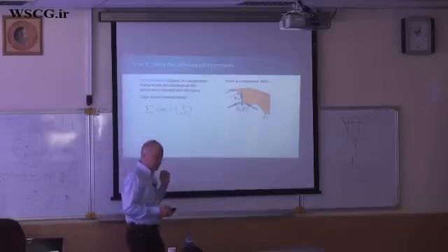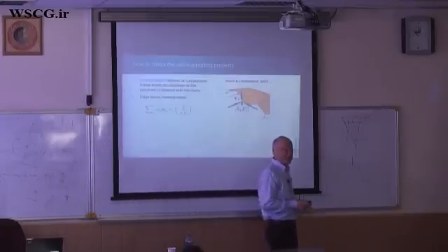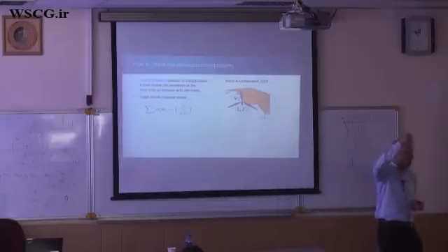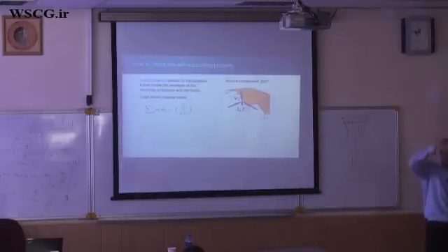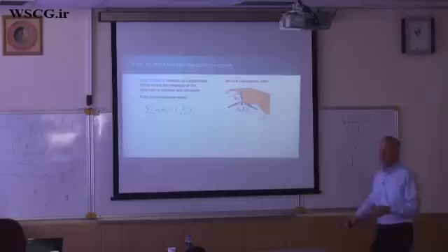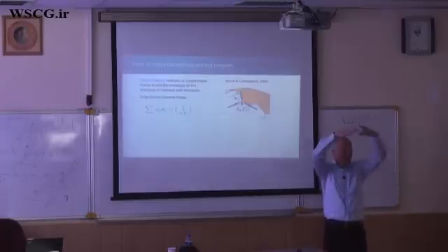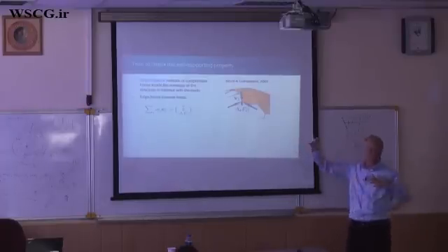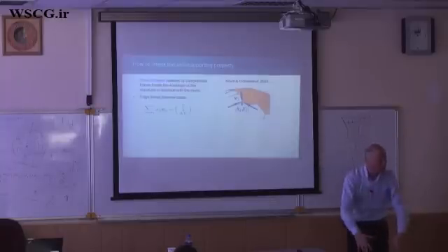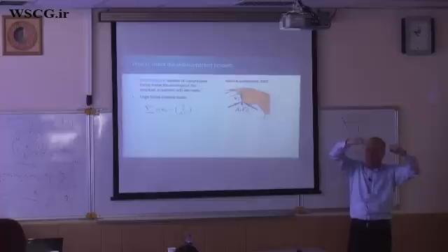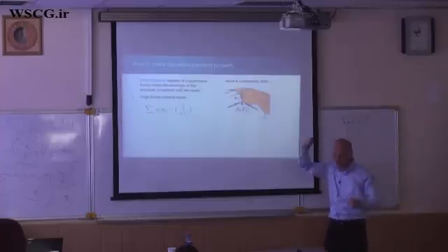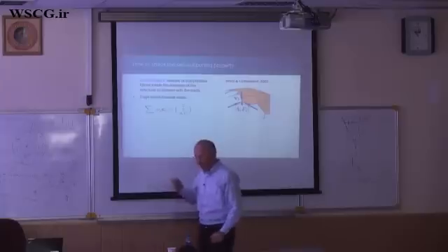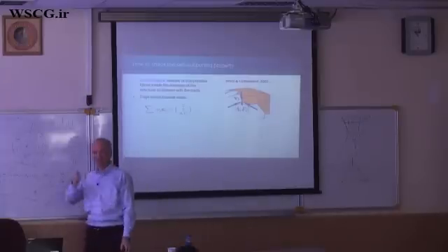I'm often asked, so if you only consider the self-weight, what happens if you put a little more weight on the structure? If there is some snowfall in my country or some sandstorm here, something like this. Yeah, so what happens? It does not mean that the structure would fall down, because if you have inside your structure such a so-called thrust network, which is in balance with the dominating load, namely the self-weight, you can still put on material and would still find a thrust network that verifies that this structure stands, but up to a certain limit.